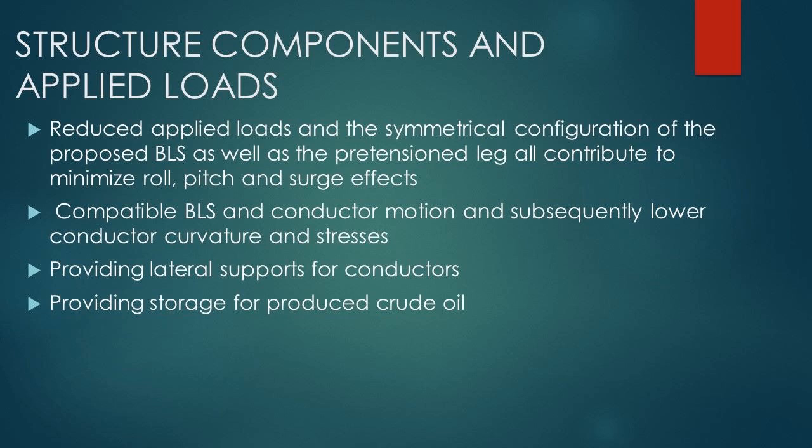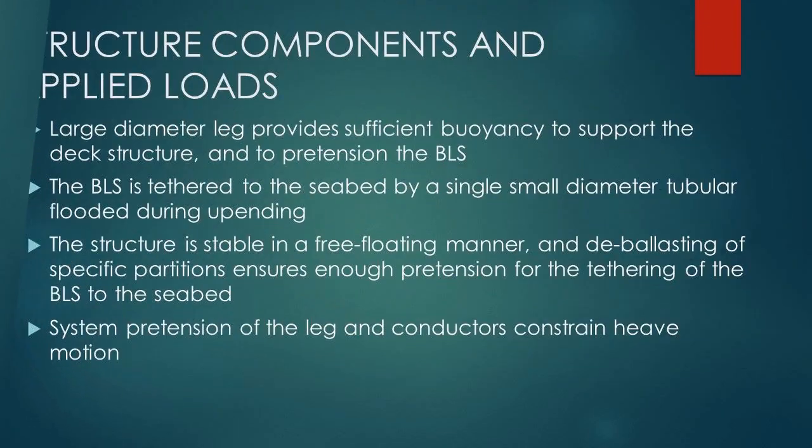Reduced applied loads and the symmetrical configuration of the proposed BLS as well as the pretensioned leg all contribute to minimize roll, pitch and surge effects. Compatible BLS and conductor motion and subsequently lower conductor curvature and stresses. Providing lateral supports for conductors. Providing storage for produced crude oil.